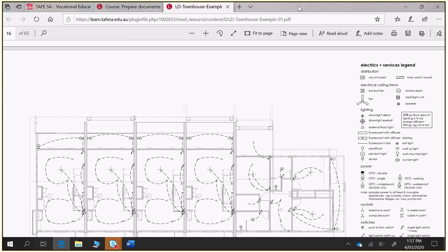to make that decision. But back to the deck: if you specify these are to be a non-combustible product, can you leave it up to the builder to choose that product within the parameters you've specified, and then you don't actually have to specify a specific brand and product on your plans? Yes, you can. Okay. Yeah, and there are many benefits in that, but it's good to also be aware of the risks in doing that as well. But the important point is, yes, combustibility. So if you've covered that, and if it's non-combustible steel framing, then your builder can.